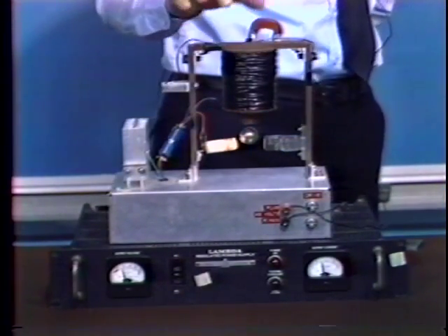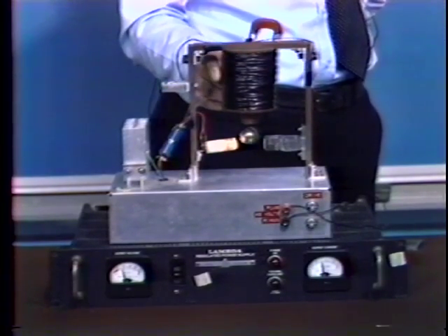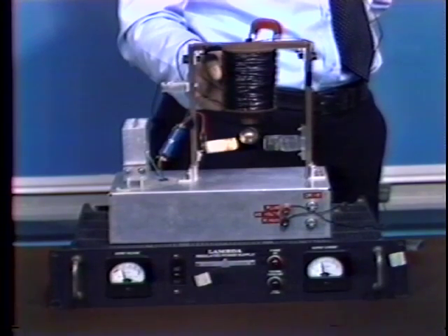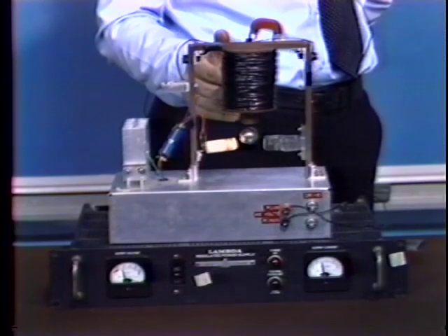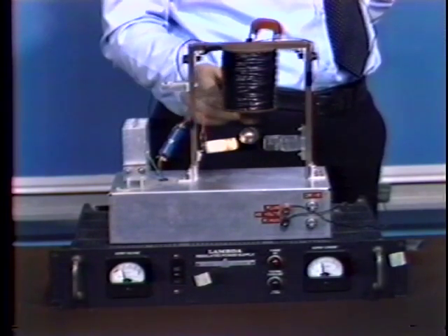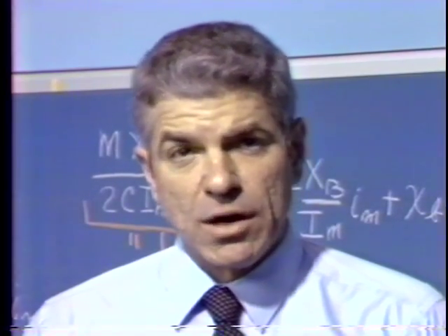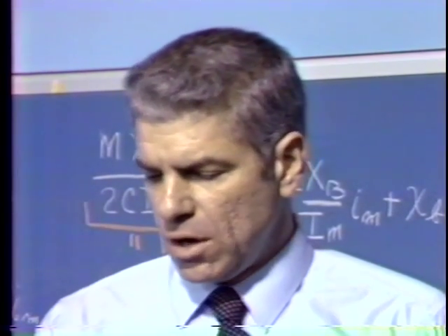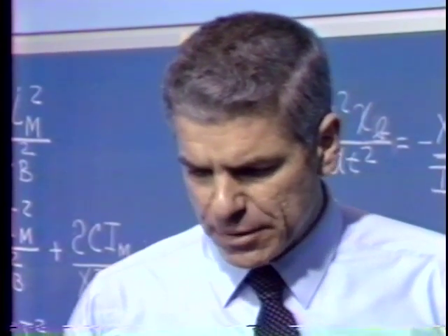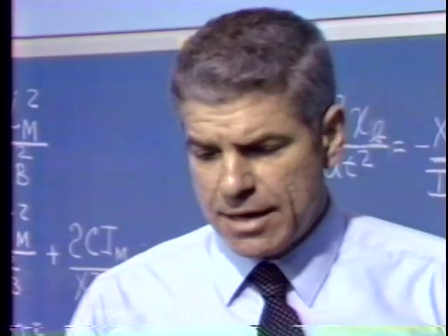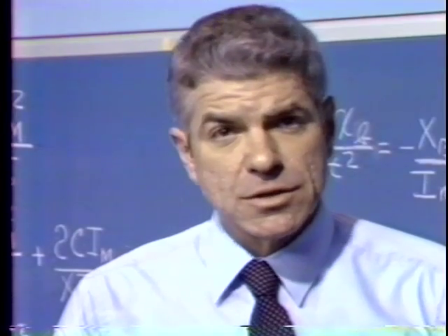And when you do that, you still have to worry about the stability of the system. Perturbations you handle with a coil in conjunction with the permanent magnet that allows you to change the total magnetic field. You add the permanent magnet field to that associated with the coil, but operating points are chosen so that the magnetic field associated with the coil at the operating point is 0, and all the coil does is basically stabilize the system. And you can put a little subsidiary loop around the thing that, with a rather long time constant, adjusts operating points to be the operating point where the coil current is 0.